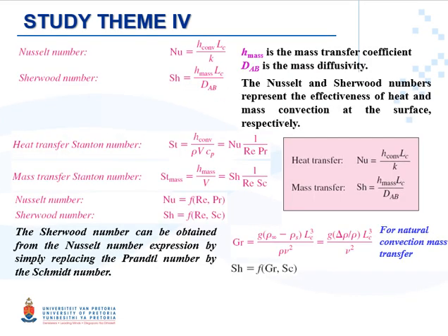We just said that the problem with convection heat transfer was H. So H was very difficult to find. That was a reason why, by using some empirical correlations, first we wanted to find Nusselt number, and after that from Nusselt number, by having Nusselt number and K and D, we could find H.